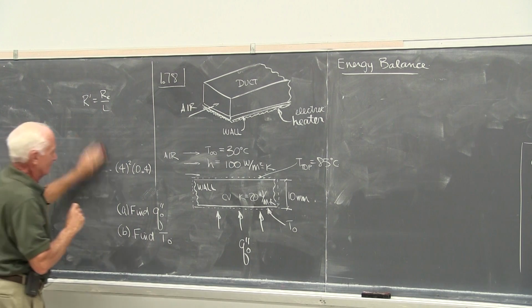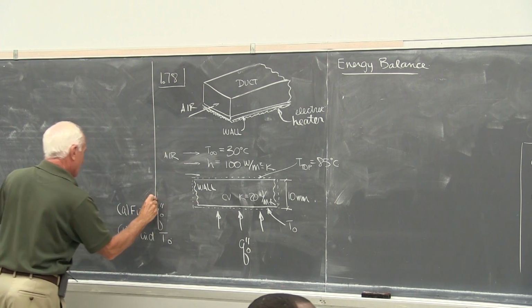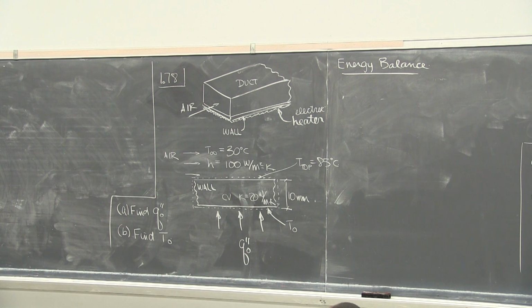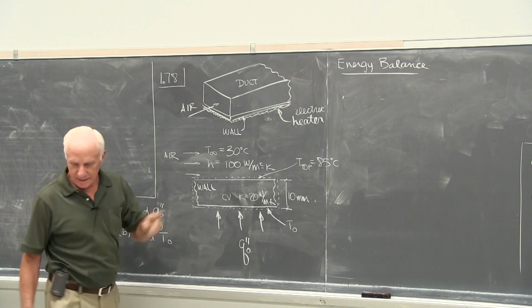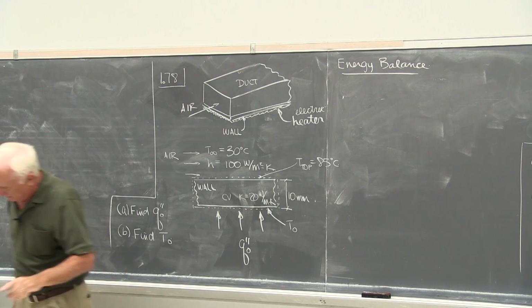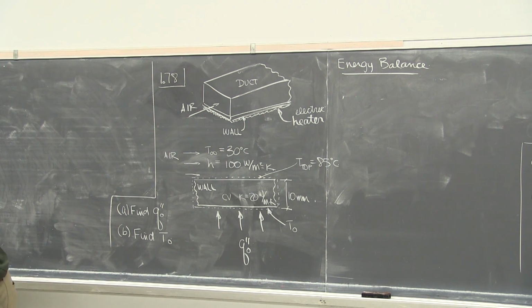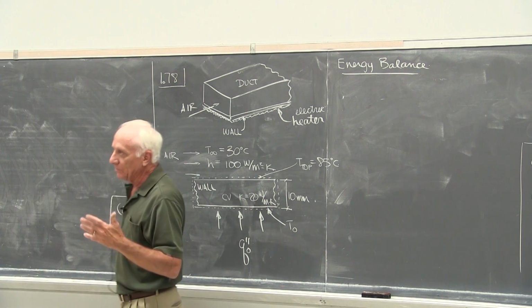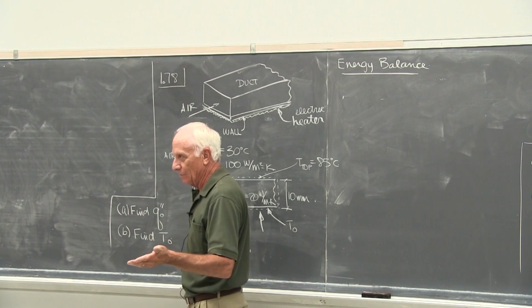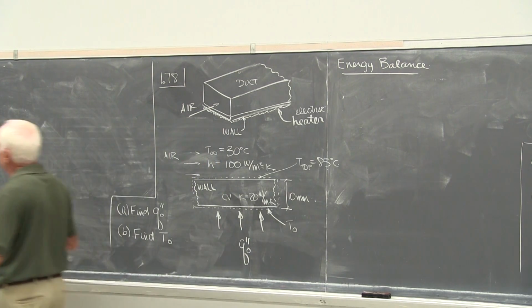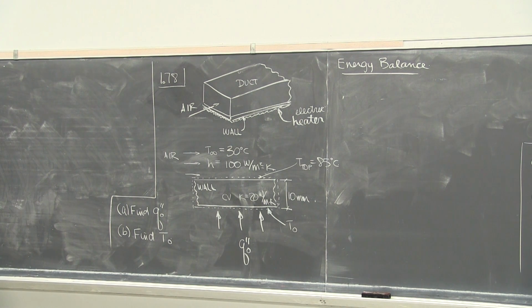Okay, now let's start back over here again. There's my control volume. It's a steady state problem. It didn't say anything about that. You heard my rule: if they don't mention time in the problem, you're allowed to say it. I think it's going to be steady state. So one of your assumptions is steady state. Okay. No change in stored energy.